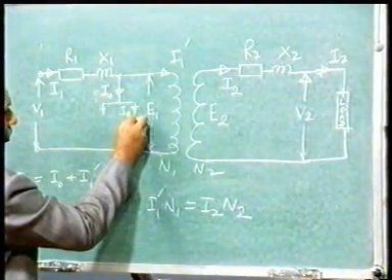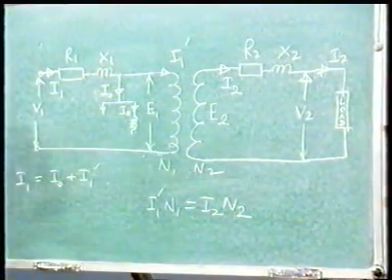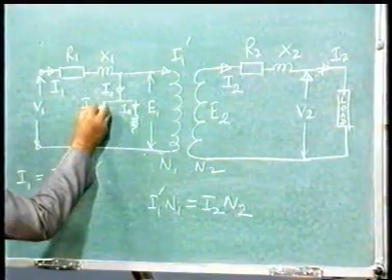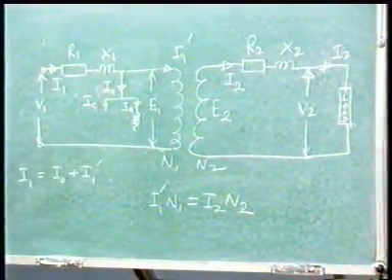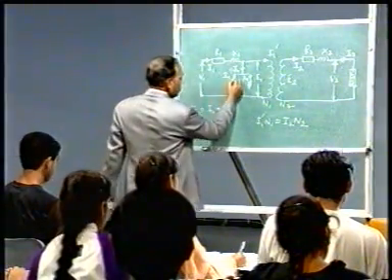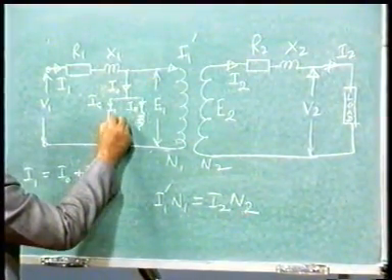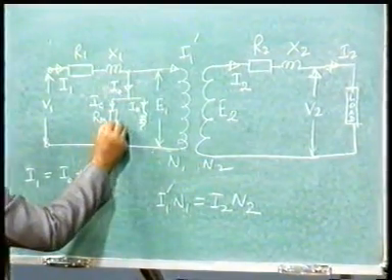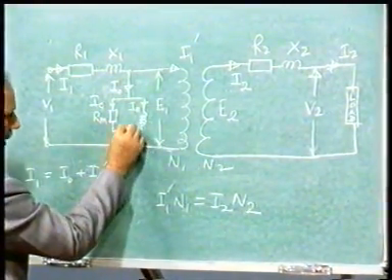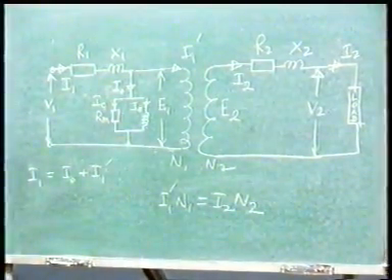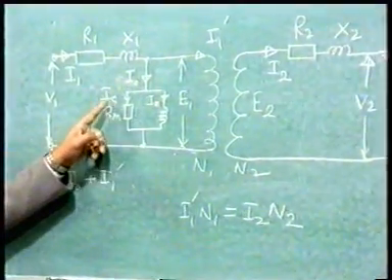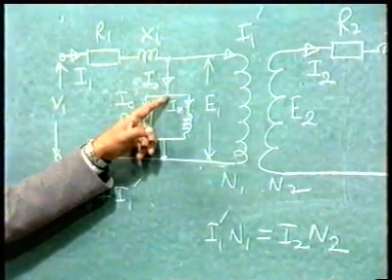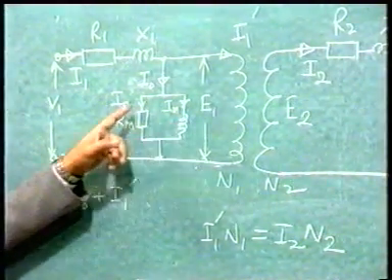IM will be shown flowing through an inductance, and IC is the current which flows through a resistance because it represents loss. Say RC or Rm. So these two together you can connect here. I0 has two components, IC plus Im. Here you apply incoming current I0 is equal to outgoing two currents Im plus IC.